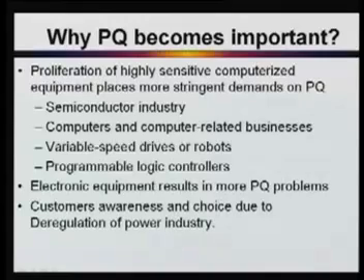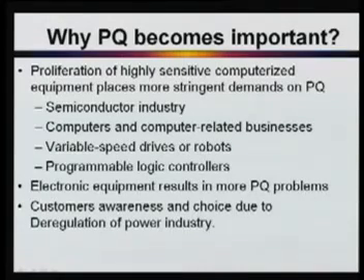Similarly, if there is phase angle displacement, there is excessive heating of three-phase devices such as motors or three-phase rectifiers. If transients are there in the power system, they may cause tripping, component failure, damage to electronic equipment, and insulation breakdown of transformers and motor loads. So transients can have a lot of effect, and it depends upon their duration, magnitude, and frequency. Transients are very common in the power system. At the same time, they are very dangerous to power system equipment, and also very dangerous for insulation failure.